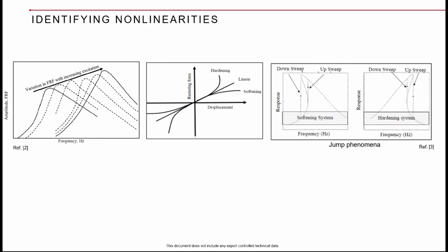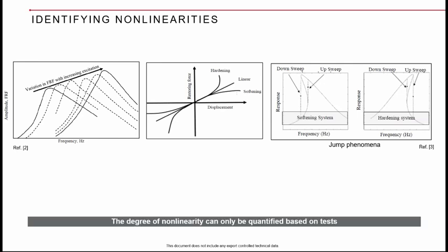If in your product family this kind of nonlinearity is quite critical, you characterize it through system identification by conducting sufficient tests, and establish transfer functions to linearize that nonlinearity, and conquer that within your linear world of modal analysis by having adequate behavior captured with this kind of assumptions. Okay. Any questions here?